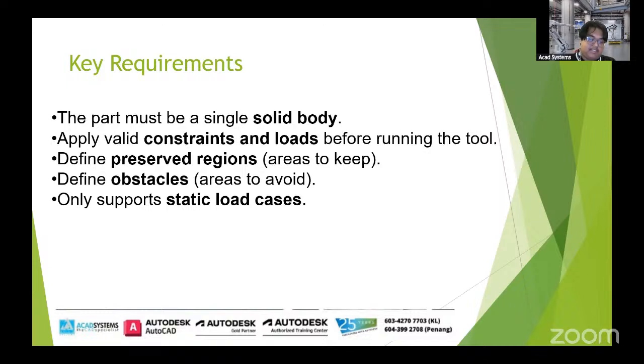So basically what that means is that we can't really use shape generator for parts that we want to optimize around thermal loads or dynamic loads or just time-based scenarios. So these are the things you have to keep in mind and make sure you model your parts around these limitations.